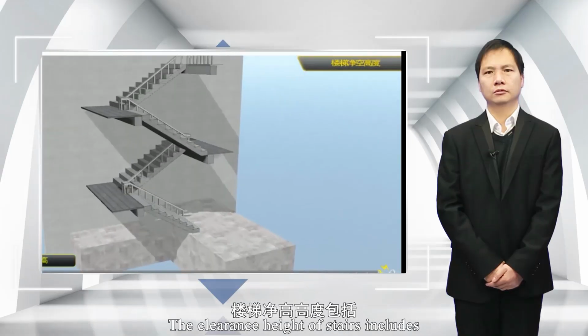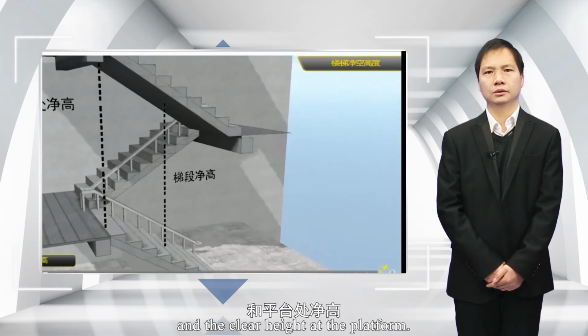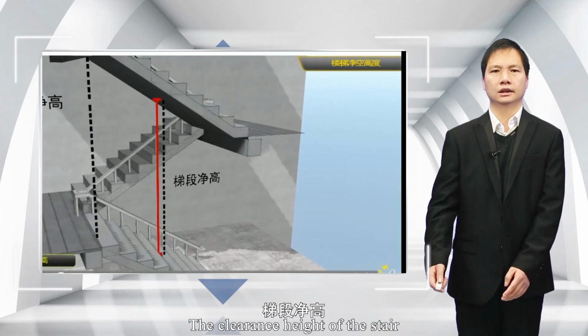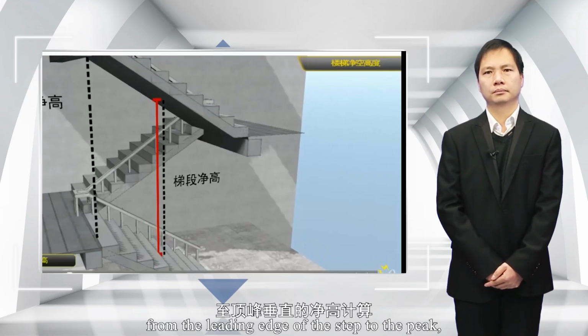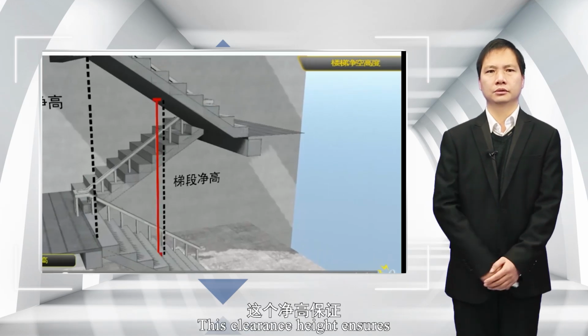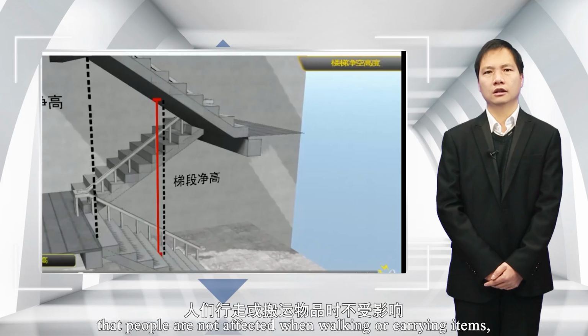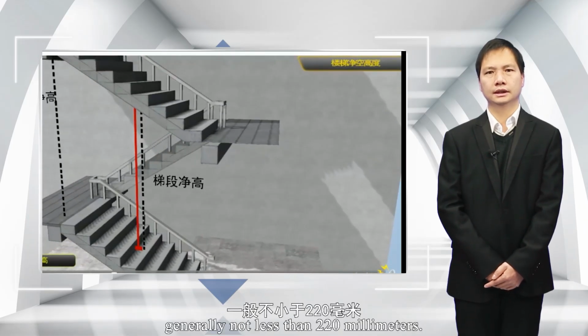The clearance height of stairs includes the clearance height of the stair section and the clear height of the platform. The clearance height of the stair flight is calculated based on the vertical clear height from the leading edge of the step to the ceiling. This clearance height ensures that people are not affected when walking or carrying items, generally not less than 2200 millimeters.